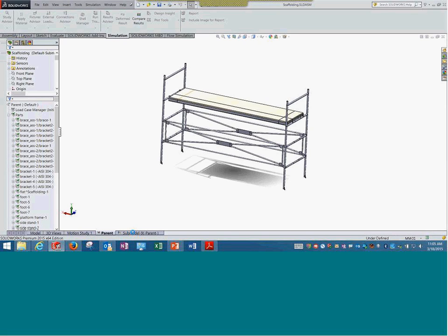So take a submodel, it is automatically creating a new configuration, and it is going to suppress all other parts and keep only those components that have been used in this submodel, and those parts will be analyzed at the local level. That's it. And I'll quickly show you the place where these options are, and how to proceed. Waiting for it to respond.